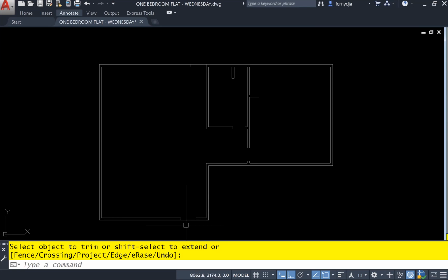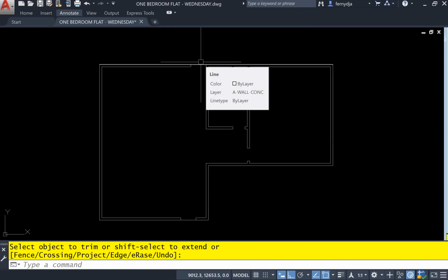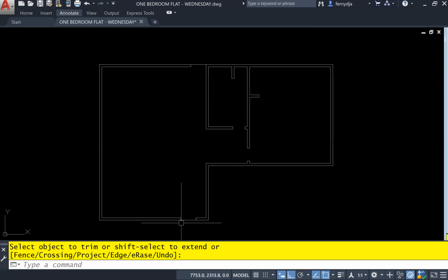So if you trim out both lines, then you are suggesting that both ground and floor is at the same level. That means you live in a river course. If rainfall, water does run right through the building because there is no step up. So we need to leave that line to indicate that there is a step up. So do not trim the outside lines for front door, back door.